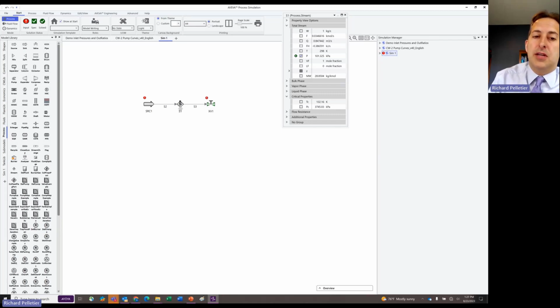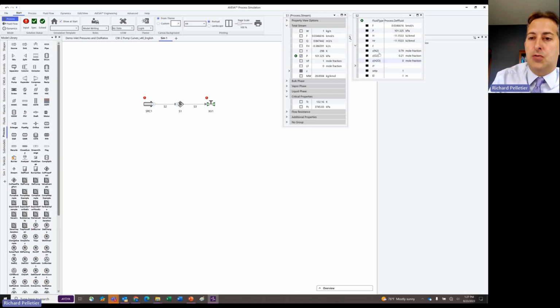Well, now that we've shown this connection model, we can look at either one of these two connections that remain, and we can see what's normally shown or what's normally transferred. And you can see it's a lot smaller subset of information here, right? It's what fluid am I using? Molar flow rate, pressure, enthalpy, and composition are the main properties. There's a couple of other properties for reverse conditions and a couple other things that are required for very specific types of calculations like elevation calculations, right? But outside of that, this is it, right?